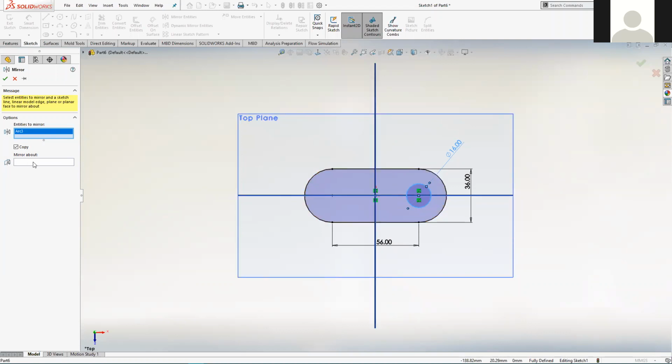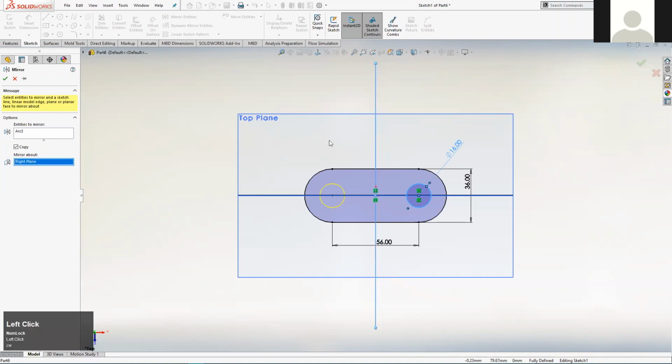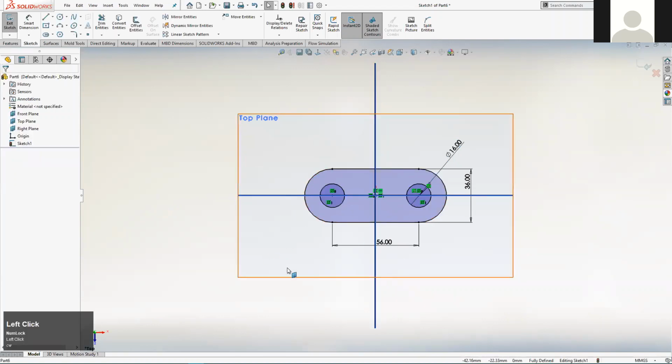Then we're going to click in the second box, and define that plane there, which, placing that plane where we have relative to our sketch, is helping us now, so that we can just click on that plane. We get a preview in yellow, as most of the previews are in SolidWorks. If we're happy with that, you just click on the green tick.